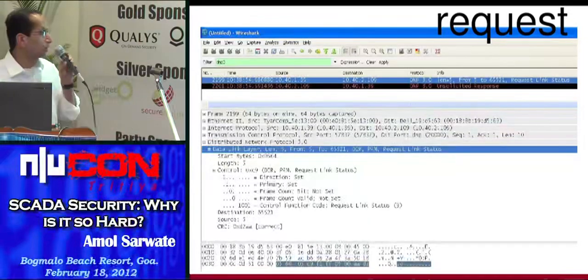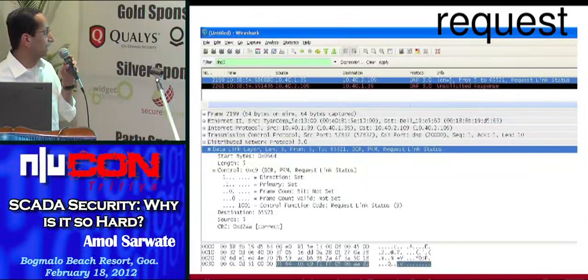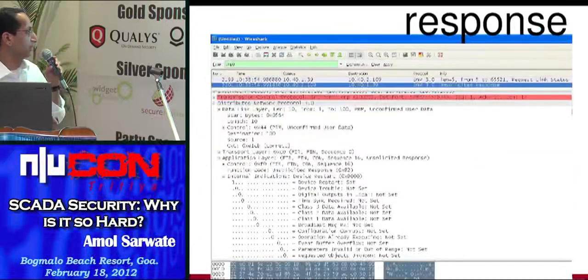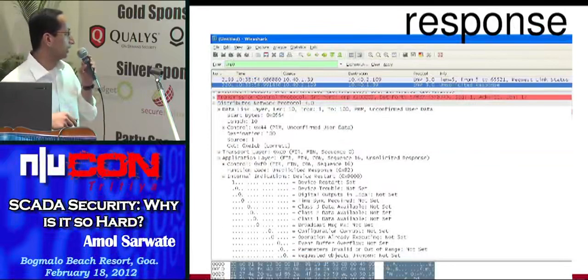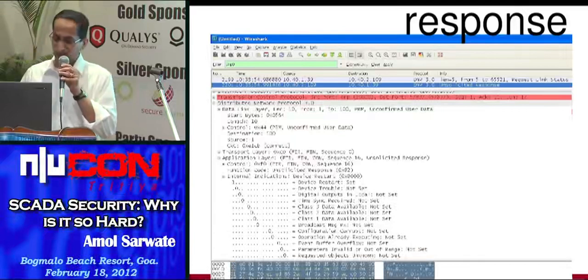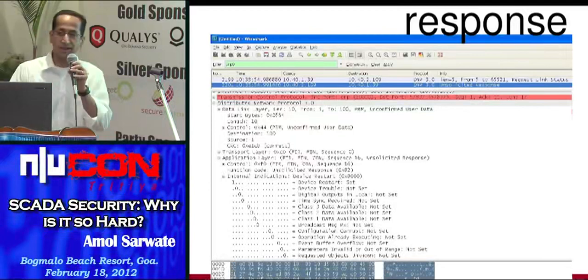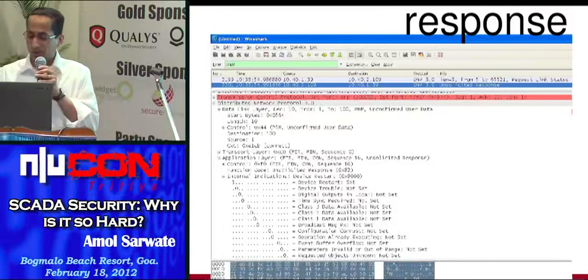When you send this request, what you see is basically this. You send the request asking for the status of the link with these various parameters, and you get a DNP3 unsolicited response saying that, okay, the link is up. And again, it has various flags indicating the status of the link. So without going into too many details, it's again a simple client-server protocol, just a little more recent and more advanced than Modbus.